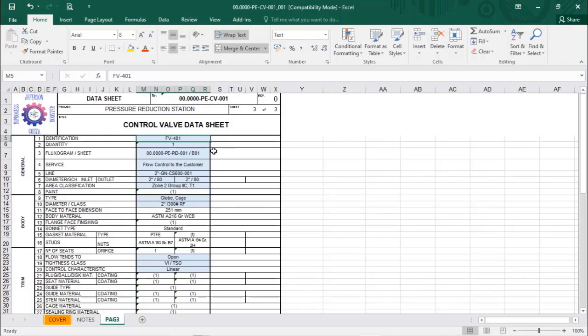In this case, I want to control flow, so because of that I use FV, and you need to inform how many valves you want, and there are processes that we need to have a standby valve, and if that is the case, instead of buying just one valve, you would buy two, and eventually the tag, instead of FV 401 would be FV 401A, and also FV 401B.